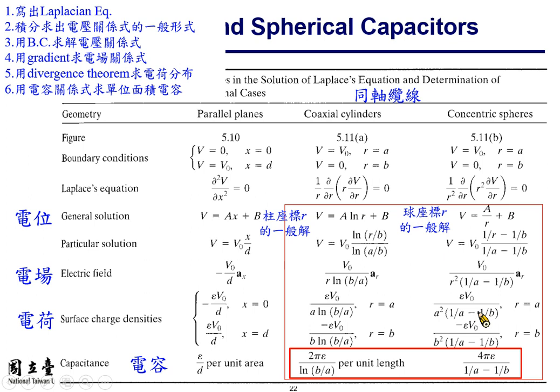And the general solution for coaxial geometry is V equals A times log of R plus B. Okay, so it's different to rectangular coordinate system. As a result, the specific solution for the voltage is different. And the expression for the electrical field intensity, which is acquired by taking the gradient, is different as well.